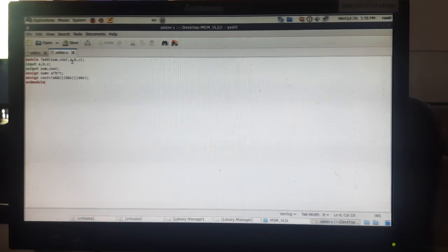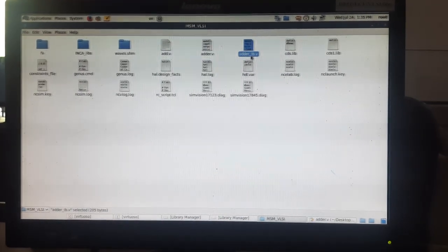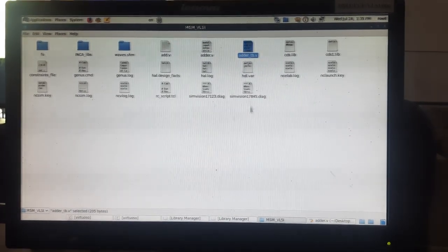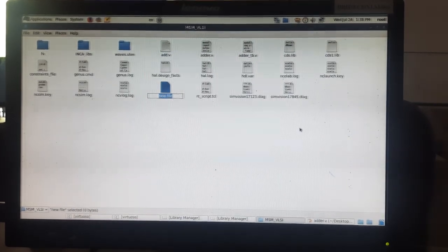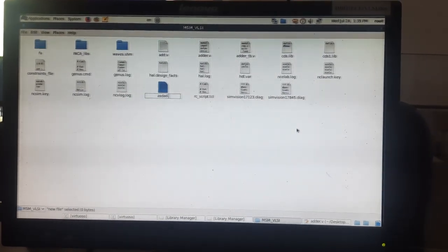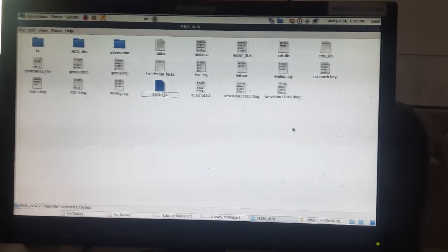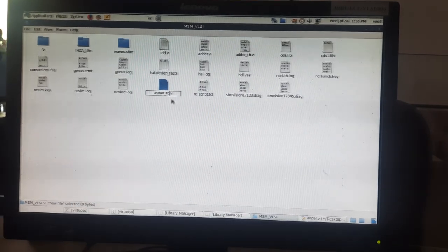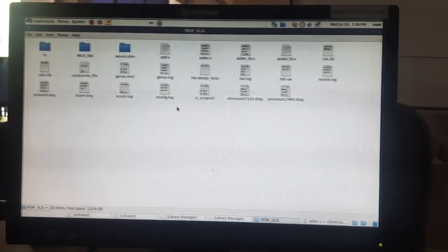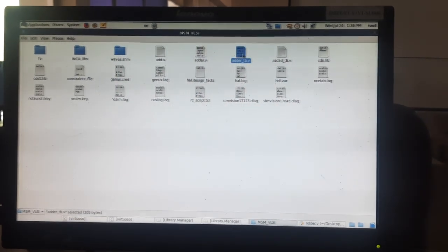In parallel to this, we need to create one more file. And look here, adder_tb.v. So again a .v file. I taught you how to create a file: create document, empty file. So type some name. .v is mandatory, but in this we need to add _tb. So underscore anything underscore tb.v. So such a file should be created. I already created one. So adder_tb.v is this file.